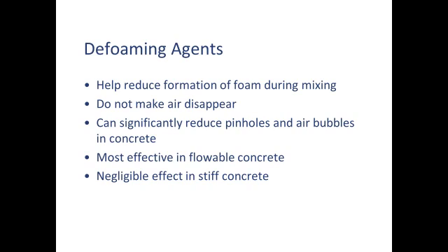There are many different ingredients that can cause foaming. Some superplasticizers can cause foaming. There can be foaming from your pigments, from just general ingredients. And defoamers don't make the air go away. What they do is help break up the air bubbles so that instead of having a stable foam, like when you shampoo your hair in the morning in the shower, you can grab a handful of that foam and mash it around, and the foam's very stable. The bubbles don't break up easily.